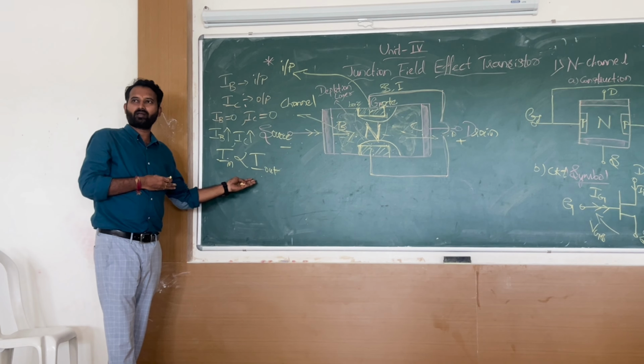Now listen here. Now let me explain why JFET is called a voltage operated device. Focus here. Now what is this terminal? Gate terminal. Gate is the input terminal. So here we are applying a certain kind of voltage. Your input is responsible for causing a change in output current. Your output is your drain current.